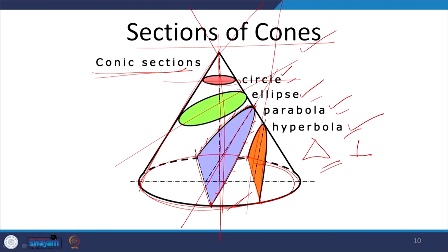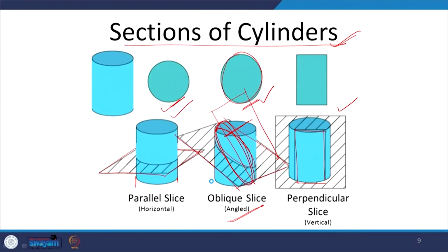Every time I talk about cylinders or cones, as we had talked about circles, just be sure that we are going to divide the circle or the base of the cone along its periphery into a certain number of equal parts, and every time we draw this, it will be the projection of these points. So, if it is an ellipse and we have inclined it, what happens?